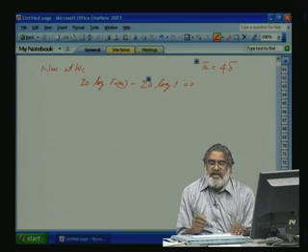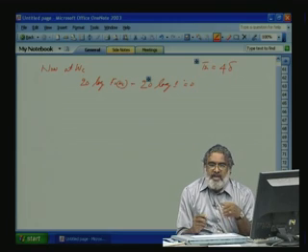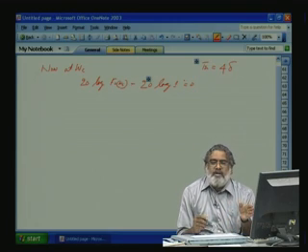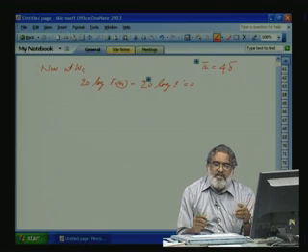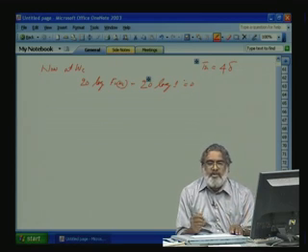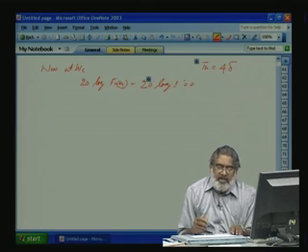Why are we taking unity gain? We want the feedback loop, connected to the controller input where the reference and feedback come, so that for all frequency variation of the input, the feedback should follow the input.